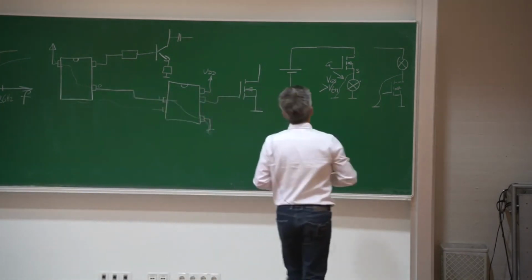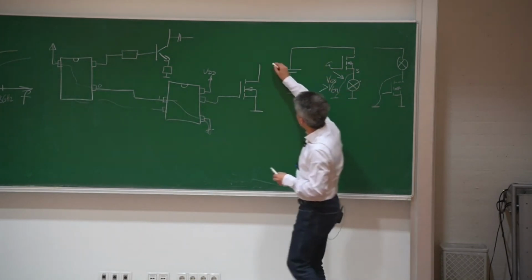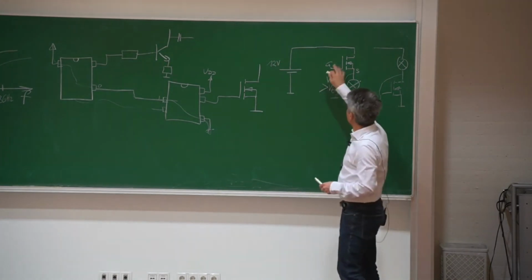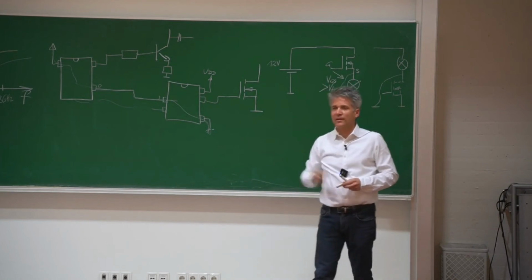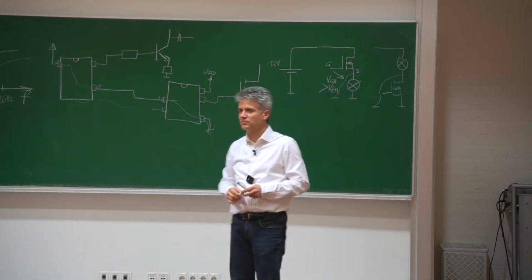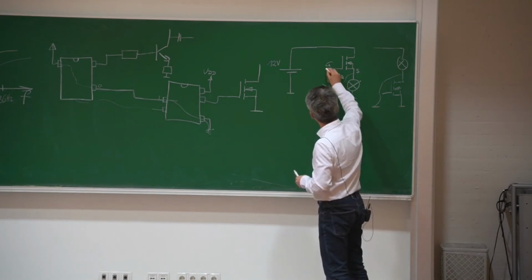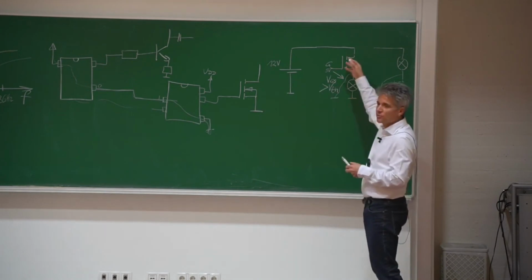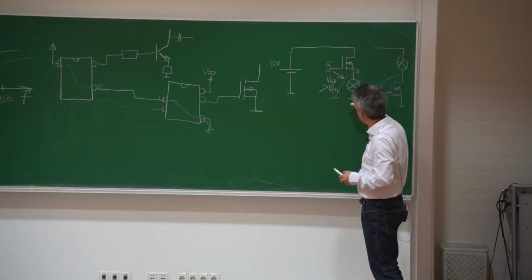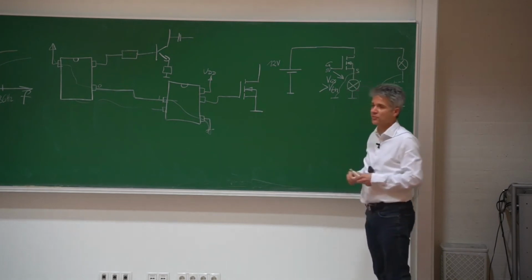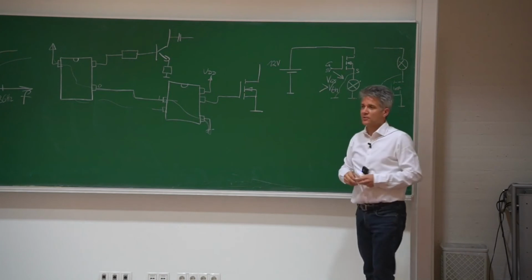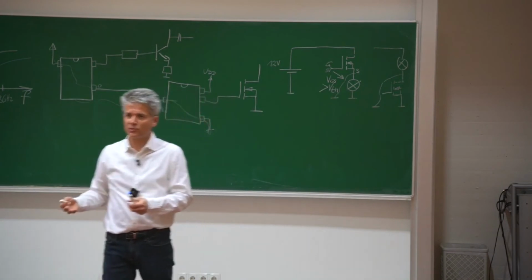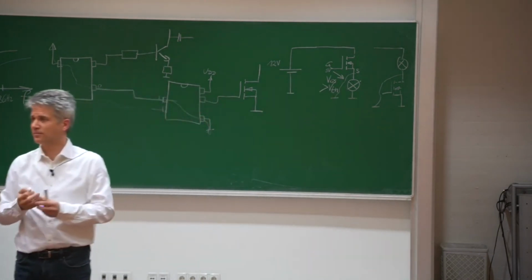Okay, so now comes the problem. If I have my 12-volt power supply here, which is there in my car, here is my control module, and I'm just generating a 5-volt gate signal. And I'm applying 5 volt here. The transistor is at the beginning not turned on, so I have ground potential here, which means that also the source potential is ground. So my VGS is 5 volt. I think it's clear. So VGS is bigger than the threshold voltage.